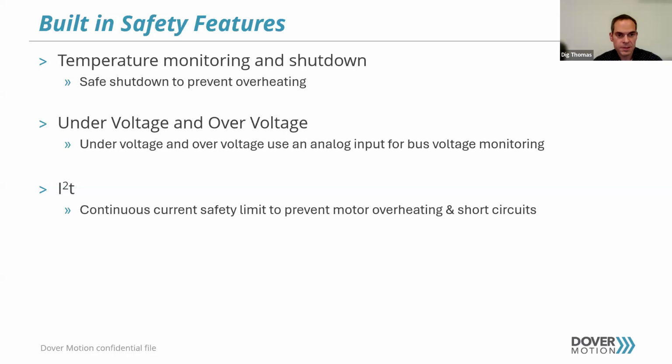Sure. Typically, we set that here at the factory based on which model stage and which type of motor is in there. It's really a function of what is the peak current and the continuous current, and what levels of accumulated energy, as you put it, we're comfortable with. We test that here and then basically bake that into the standard product.